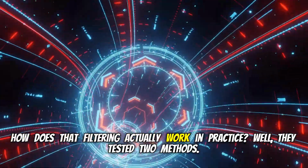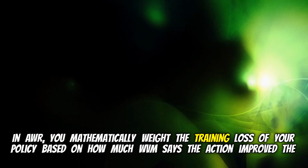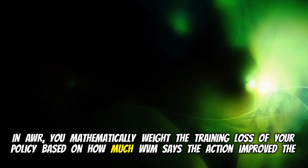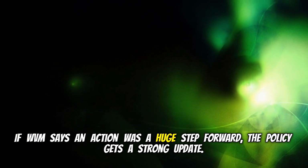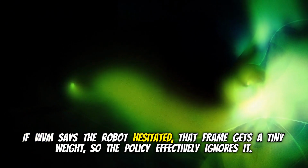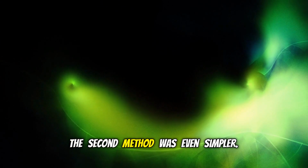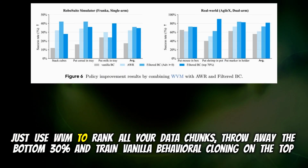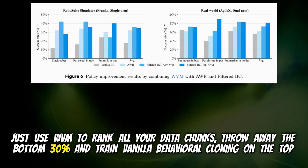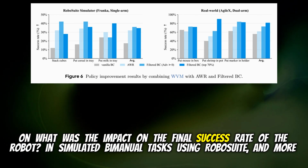How does that filtering actually work in practice? Well, they tested two methods. The first is advantage-weighted regression, or AWR. In AWR, you mathematically weight the training loss of your policy based on how much WVM says the action improved the task progress. If WVM says an action was a huge step forward, the policy gets a strong update. If WVM says the robot hesitated, that frame gets a tiny weight, so the policy effectively ignores it. That makes sense. The second method was even simpler. Just use WVM to rank all your data chunks, throw away the bottom 30%, and train vanilla behavioral cloning on the top 70%. What was the impact on the final success rate of the robot?